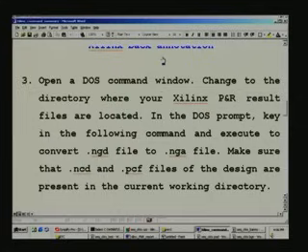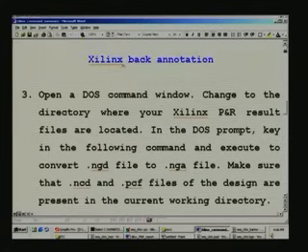And we'll continue, we'll start rather, the Xilinx back annotation. The purpose of back annotation is to incorporate the gate delays, and then go on to the simulator and see actually the gate delays shown as a waveform there. In the timing diagram you can see the real delays, and we have already seen in the synthesis tool, in the waveform analysis prior to this, that timing is slightly affected even after optimization. So in place and route it must be more so.